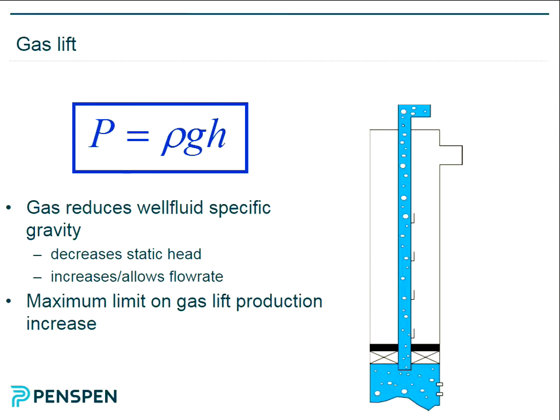That's height in meters, and this is pressure in psi. This is the pressure inside of the pipeline, basically. But you can see as it goes up the mountain, you can find that it goes below the vapor pressure. So you get what they call a vapor lock. You get gas coming out of solution and actually causing multi-phase flow and reducing efficiency. So that's actually a bad thing for a pipeline. You'll reduce the transportation efficiency of the pipeline.